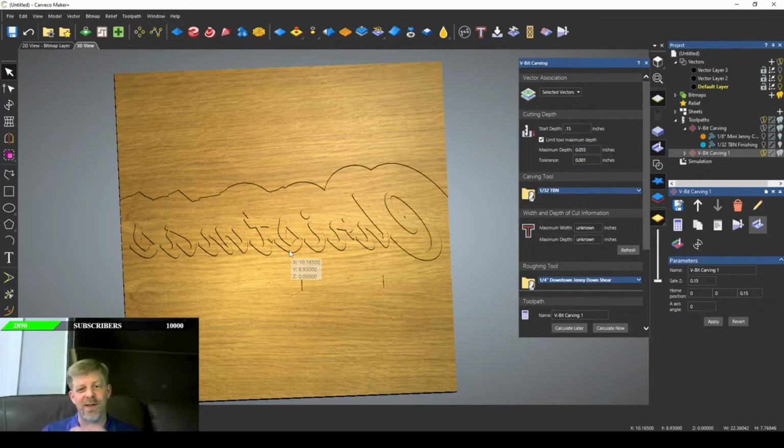Clamping pressure is key. When you press these two together, the male and the female, I have a hydraulic jack. It's like a car jack, and it's two boards that sandwich it together in a frame, and I just jack that car jack down and smash it just about as hard as I can get. You have to be careful with that, because you can crack your material, especially if you have a lot cut out and a lot glued together. If those walls are thin, you want to make sure you have good, even pressure on your whole board.